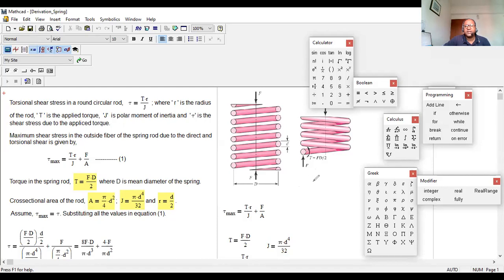One is F, the other one is torque. So both will create shear, obviously F working parallel to the cross section, and torque also creates torsional shear stress. So that means this wire right over here, the shear stress will be the same all around the body, right?